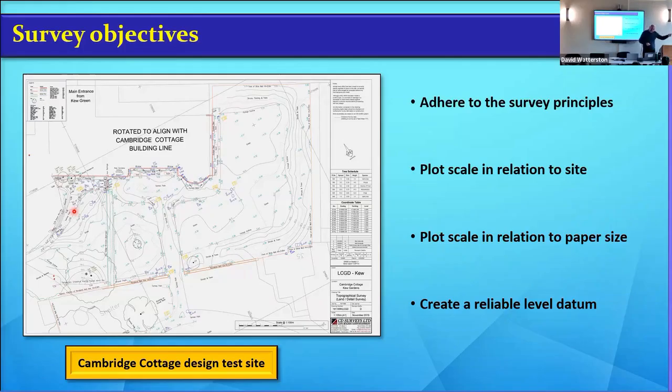If I produce it at 1:10 scale, you could then measure from there to there and say I'm 2 mils out. And then I would say, well, hang about. I'm allowed 3 millimeters at 1:10 because it was 30 mil at 1:100. So you're saying it's 2 mils out, I'm saying it can be 3 mils, which is the thickness of the pen line. So it's all right.